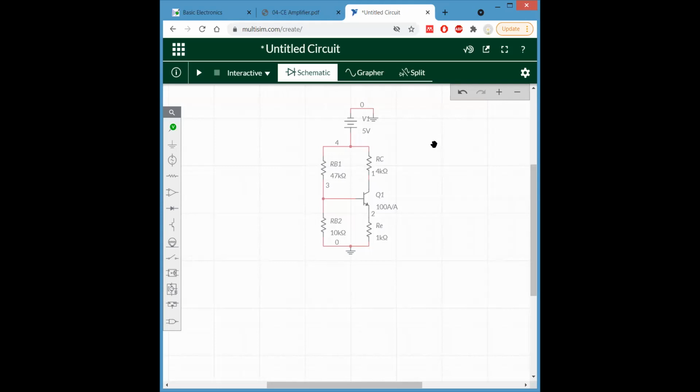In order to keep it in active region, we have to make sure one junction is forward and one is reverse. This is an NPN transistor, which you can easily identify by this notion: if you consider this is P, current is flowing from P to N, so that's why you can say NPN. This is analogous, for remembering purposes. The N side is connected to the positive terminal, which means it is in reverse bias.